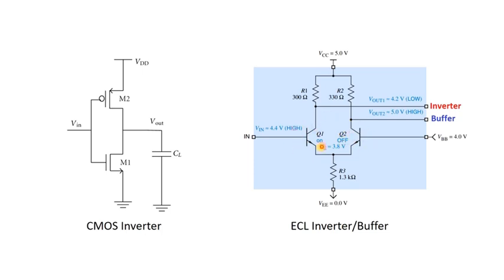The primary reason behind this high speed is the high driving capability of BJTs and their high transconductance. High transconductance of BJTs is quite clear from the exponential relationship of output current with its input voltage. However, one of the major issues for these bipolar logic families is their high power dissipation, whereas the CMOS logic family has the lowest power dissipation.